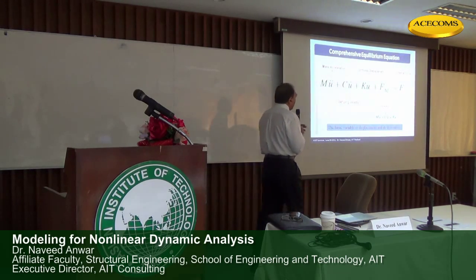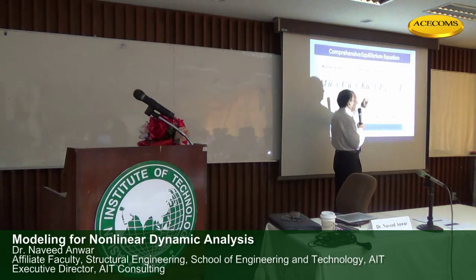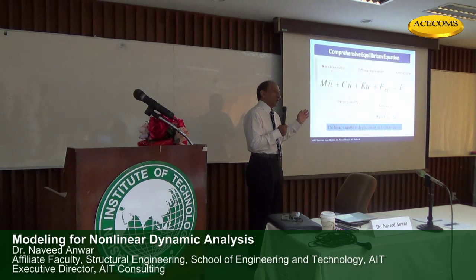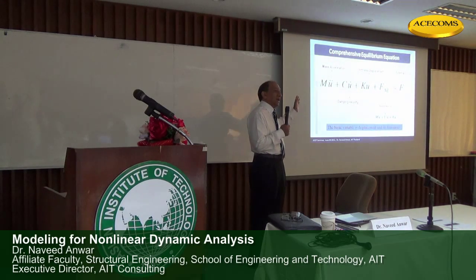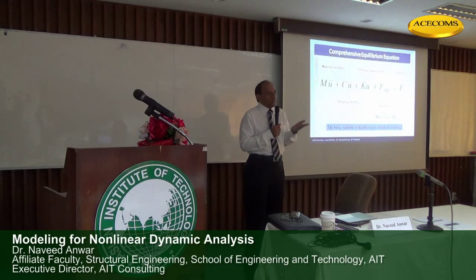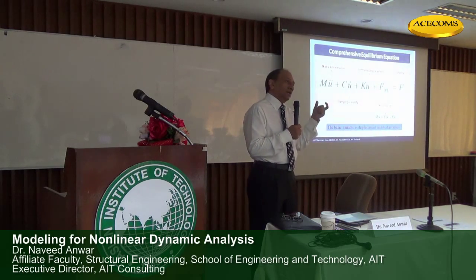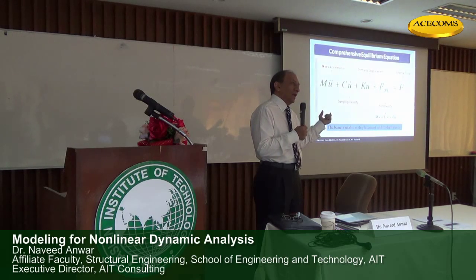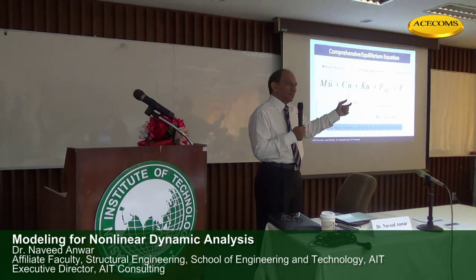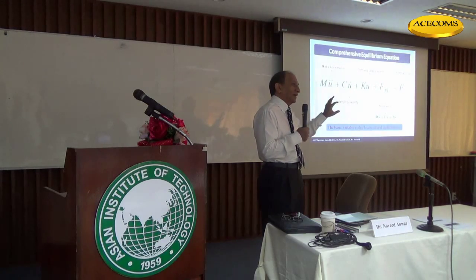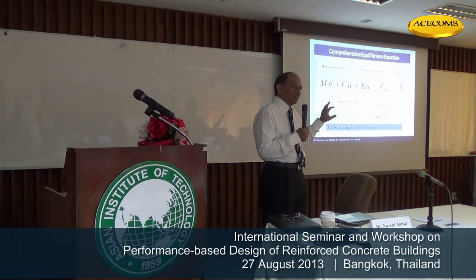The most important part of this equation is K, stiffness, and displacement. Of course, damping is also important. We will talk about that. And mass, well, mass is there. You can't do much about it, although of course you can reduce the mass. But you can control damping and you can control stiffness, which means you can control this equilibrium by those factors.